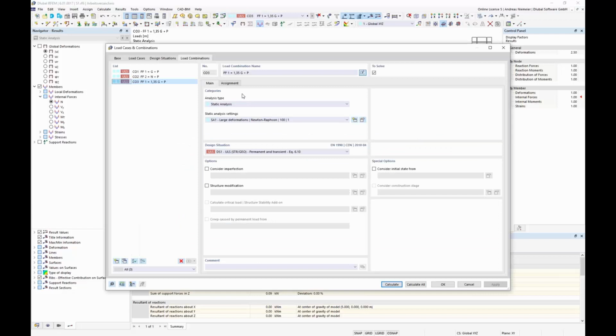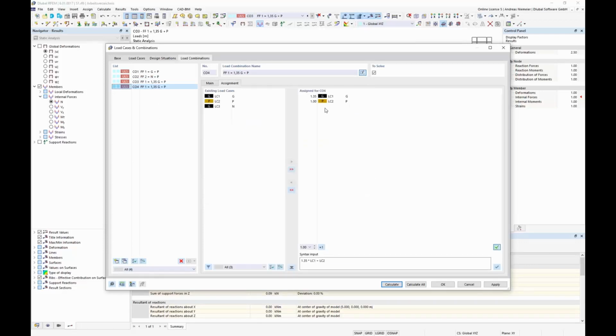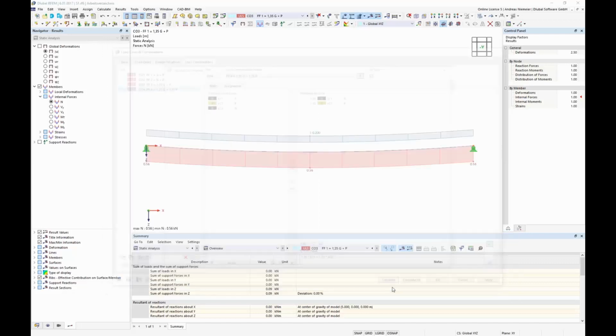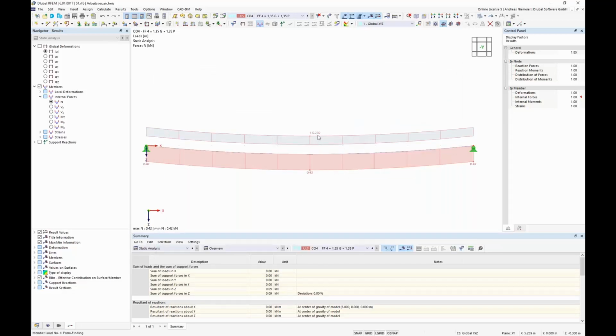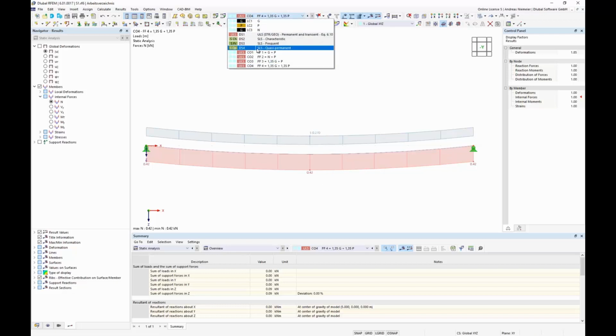Of course, we can also, let's say, scale the pre-stress. What means if I scale the pre-stress 1.35 and only for the name here 1.35 form 4, for example. This was form 3, only that we have a clear description, and calculate, then we can also scale the form finding inputs. You see not 200 and 270. What is the factor 1.35 in between with the corresponding force again. So it's an easy game to work with different shapes in one program now.